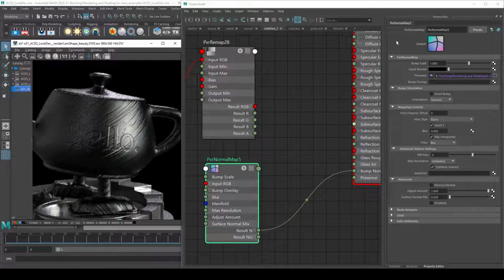So that's why I recommend you guys disable the other texture maps. But you can see with the DirectX, actually, I think the DirectX is correct. Okay, yeah, actually the DirectX is fine because the lighting is coming from the right. And so this is a cavity, so this is a raised wall and lip. So these walls are getting hit by the light, so that looks correct. And then these walls are casting shadows, which is correct. So with this one, it's the opposite, right? It almost looks like it's pushing out of the surface right here.